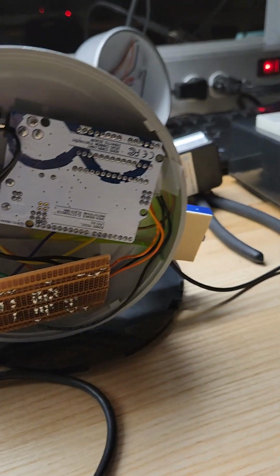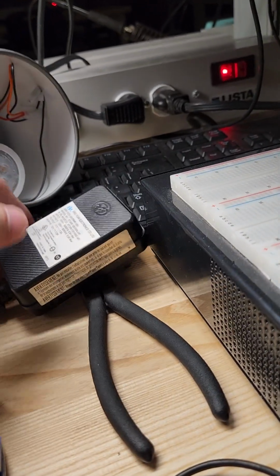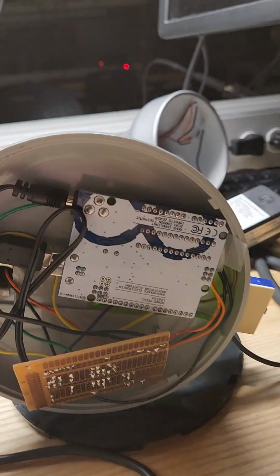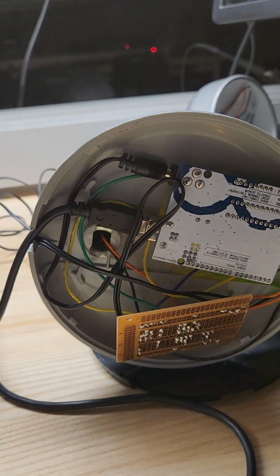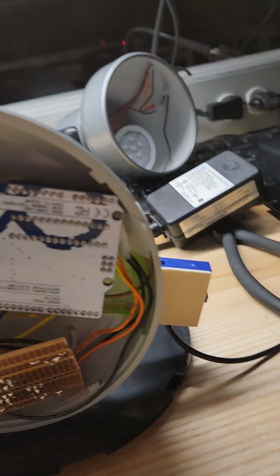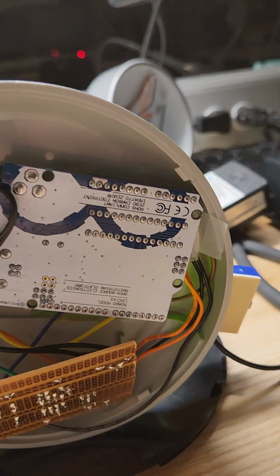That's everything about the project so far. As a brief overview, the project is the lamp with auto brightness. It's powered via this wall brick. It's connected to the computer through the USB cable. And in being connected to the computer, you're able to control the brightness, which is done by adjusting a pulse width modulation signal controlling an LED.